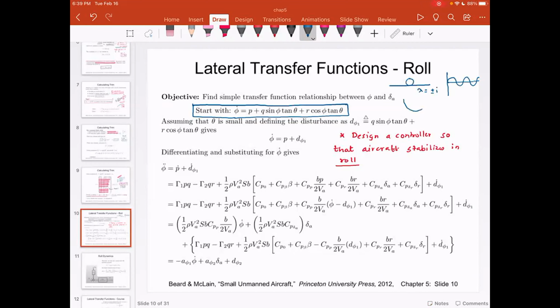Then we talked about asymptotic stability, which is like a ball in a cup, wherein over a period of time, the response dampens out. And we notice that here the eigenvalues have negative real part, and then they can have plus or minus imaginary parts. We also talked about unstable systems, wherein the system response actually grows and the eigenvalues have positive real parts. Now, this is what we studied in Robotics 1.